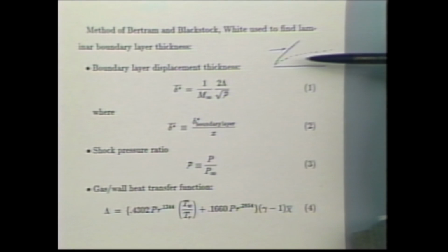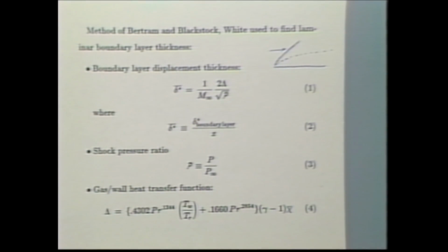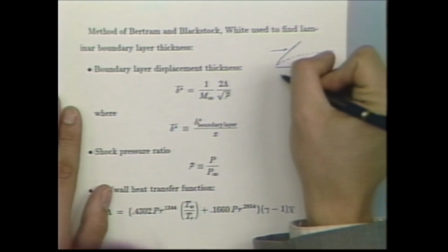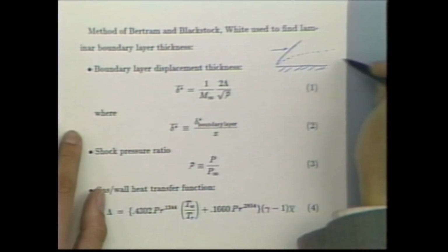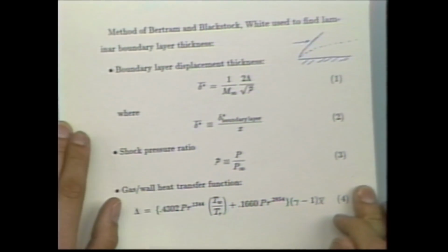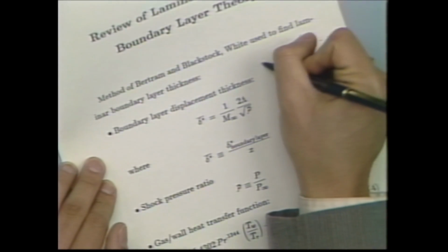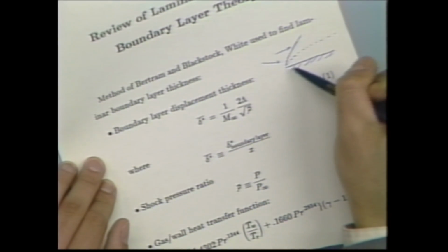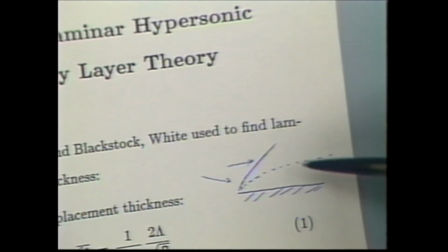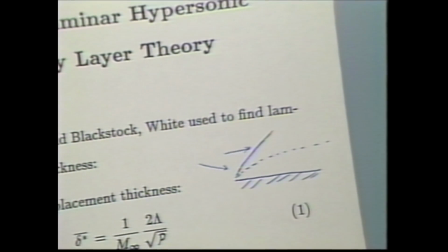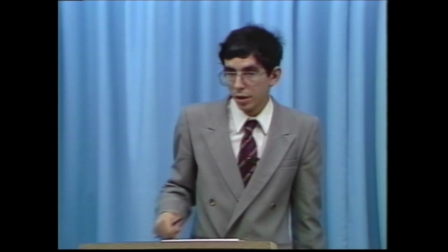Now, think about the implications of this. If I take this picture, and we'll be seeing some dramatic realizations of this, and remember this is supposed to be a surface at 0 inclination. Now think about what happens if I crank this surface up to some inclination. So I'm going to rotate the page. So now the incoming flow is at some angle. Well, you know that if you have a wedge at angle, you'll get a stronger shock, and the stronger the angle, the stronger the shock is likely to be. It means a higher pressure ratio. Higher pressure ratio means a thinner boundary layer. Now think of what that means in the context of the picture I showed of that thick boundary layer.